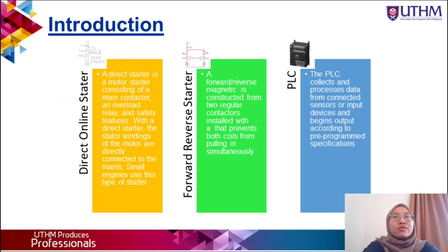Assalamualaikum. So today I will be presenting the introduction for this project. I will be talking about the direct online starter, the forward reverse starter, and also PLC. First I will talk about DOL, which is the direct online starter. A direct starter is a motor starter which consists of a main contactor, a relay and some safety features such as an MCB, main circuit breaker.